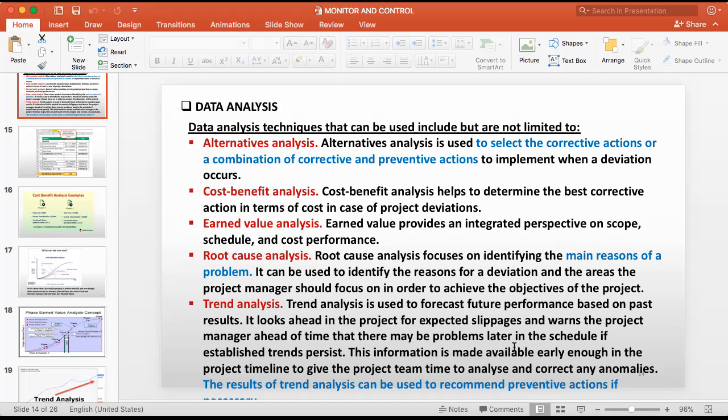If while you are doing the construction work, people show you, see my house, there are cracks because of your work, you have to investigate that. You have to find the root cause for that. Is it because of your type of machinery, or you have not taken protective steps, or your investigation is wrong?